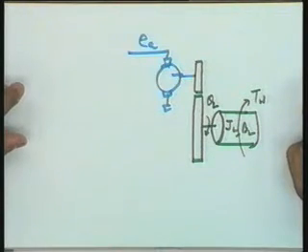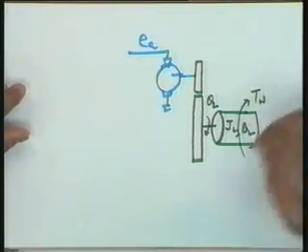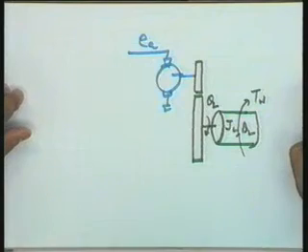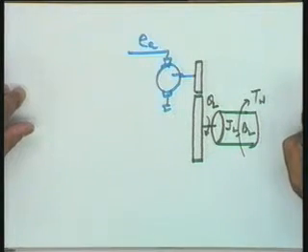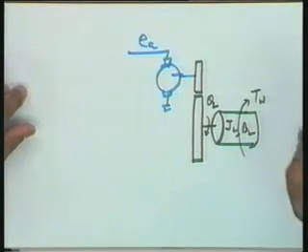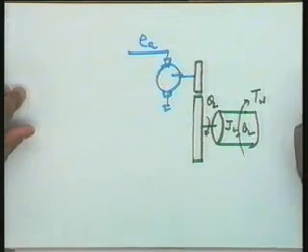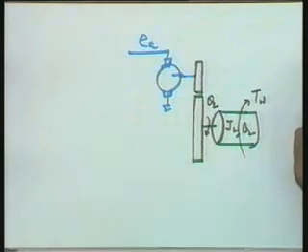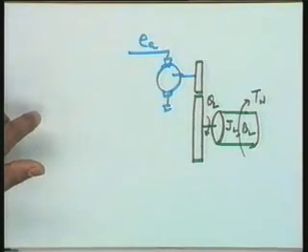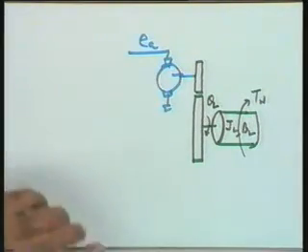The potentiometric error detector has a resolution problem. The synchro error detector has better resolution and better linearity, and it has better ruggedness. Since the contact problem is there in the potentiometric error detector, the synchro error detector is normally preferred. So with that in mind, I want to settle for a synchro error detector for this system.